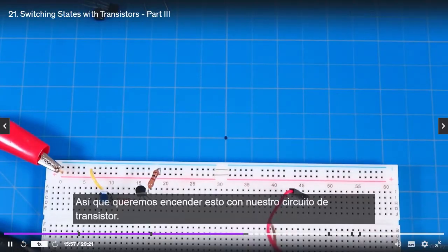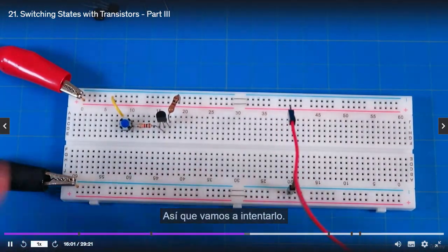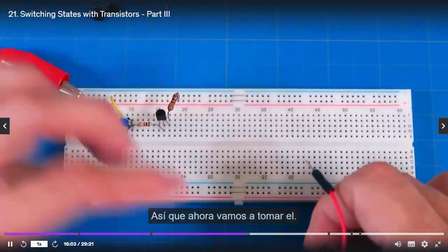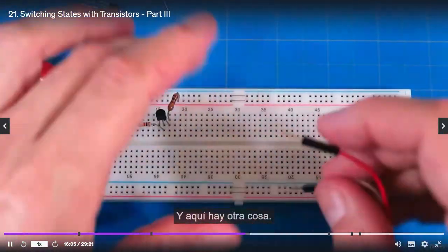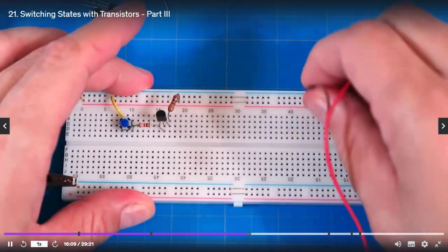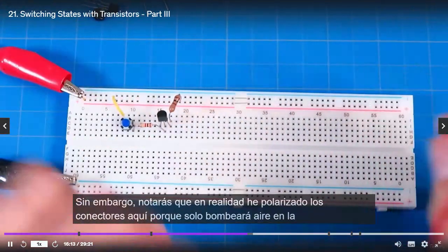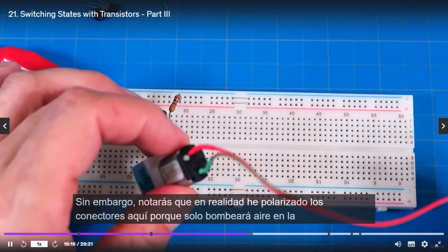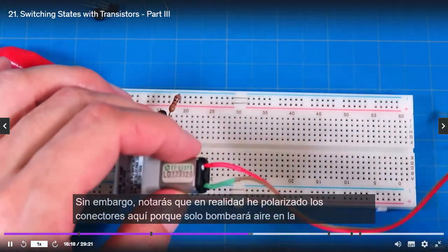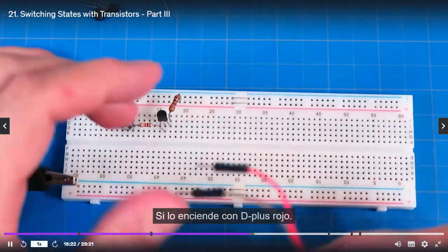So we want to turn this thing on with our transistor circuit. Can we do it? So let's give it a try. And here's another thing. Let me show you this. This motor is not polarized, so it'll go that way. It'll go that way. You notice, though, I've actually polarized the connectors here because it's only going to pump air in the proper direction if you power it with red to plus, okay?